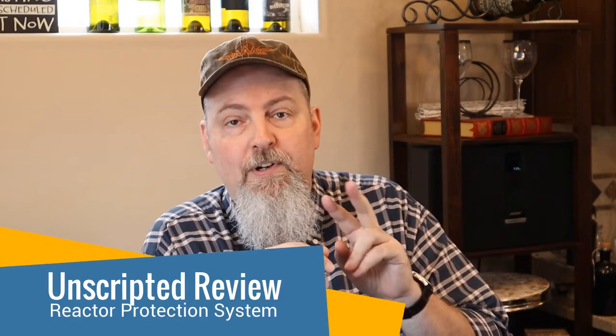So some of you had responded on the quiz that the reactor protection system was a fission product barrier. Let's talk about what reactor protection system is. Reactor protection system is 2 things in a boiling water reactor power plant. On one side, it's a logic system. So we're going to talk about logic systems next, and that's the logic system that drives our reactor scram actuation.